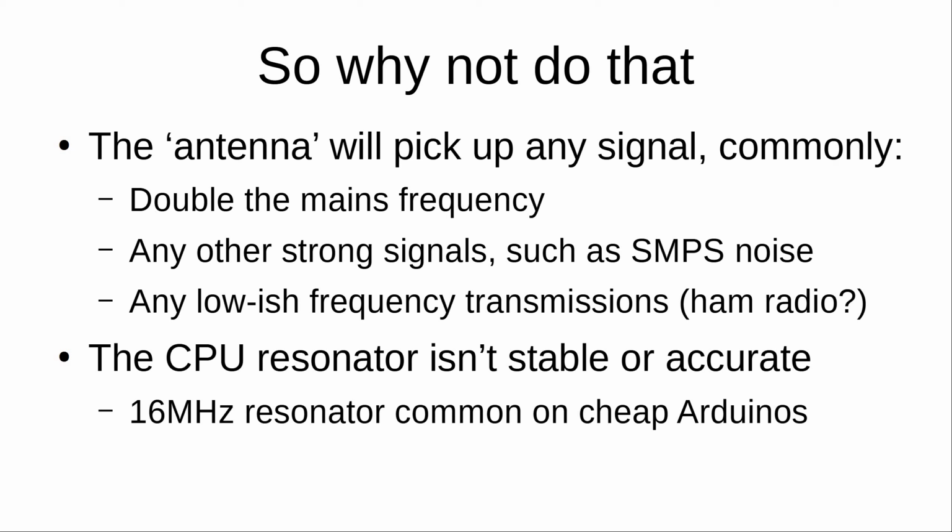Another issue is that it picks up strong switching transients from switch mode power supplies. So if you've got any power supplies sitting on the bench or in your shack, some of those were being picked up, especially the poorer quality ones with less filtering inside them. On the mains side, it was every now and again jumping to a few kilohertz and tens of kilohertz, picking up switching frequencies in some of those.